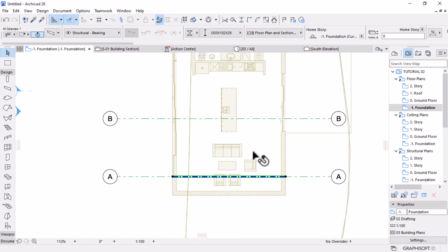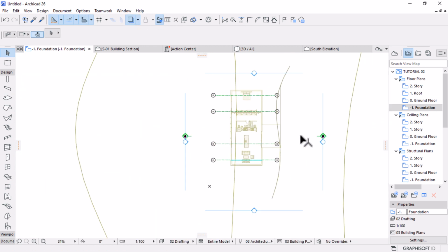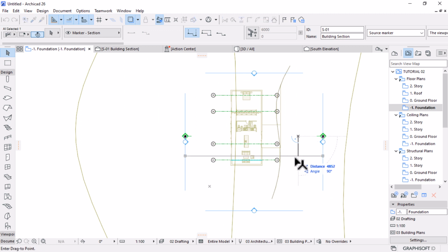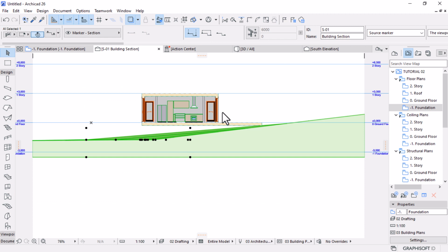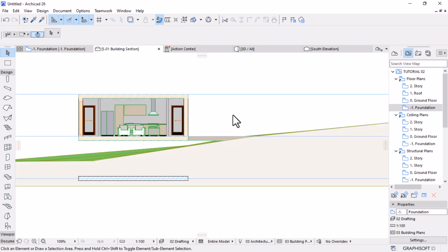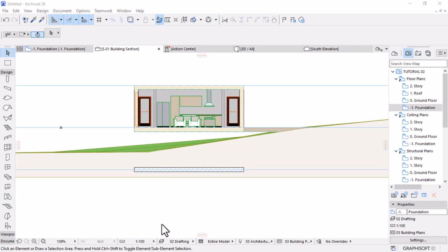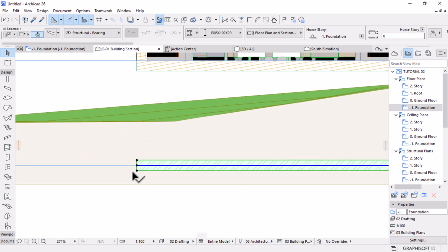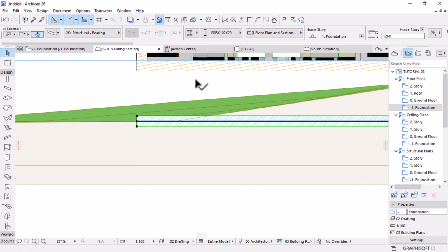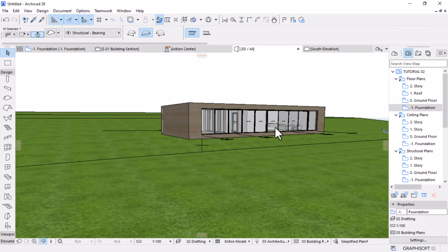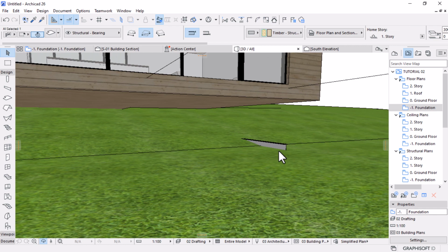Let's cut a section. Let's bring this section line to this element. Open the section view and identify the location of this. Select it and make sure it sits on the right position or location. I'll move it somewhere here so that it can be visible on 3D if you want to see. Okay, here we have,